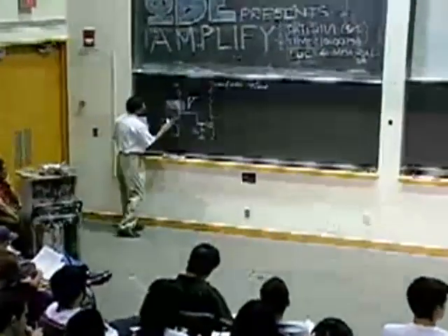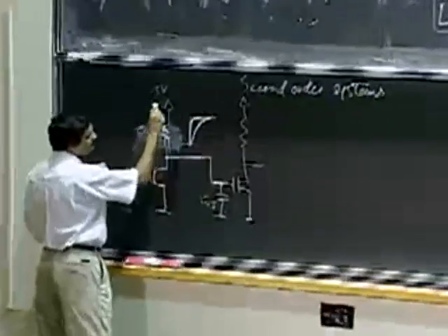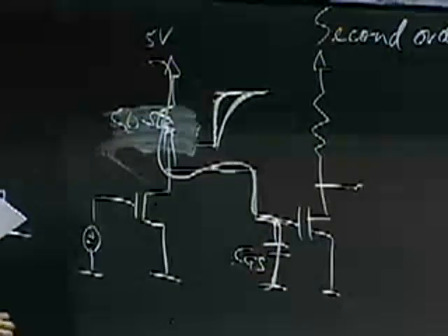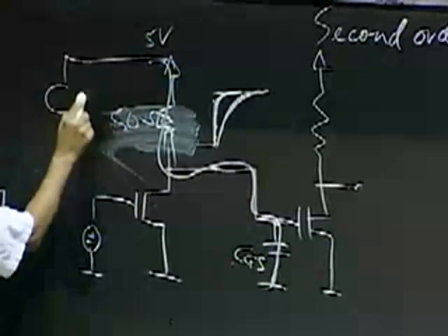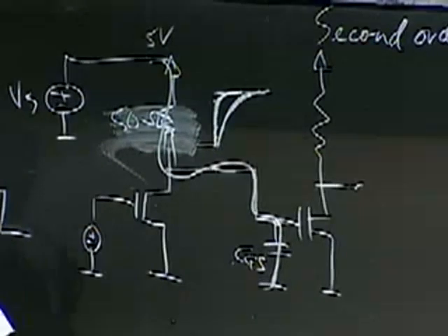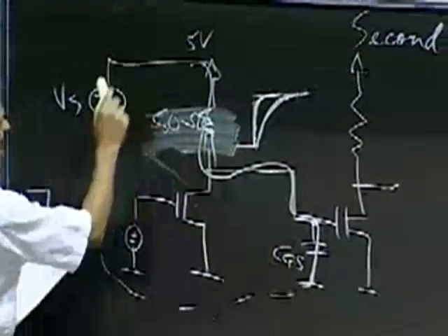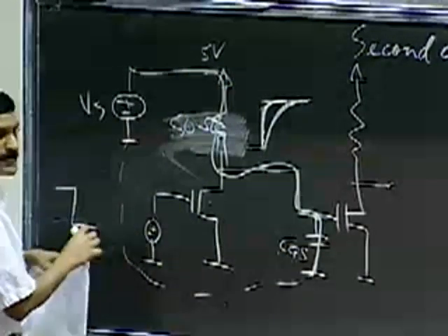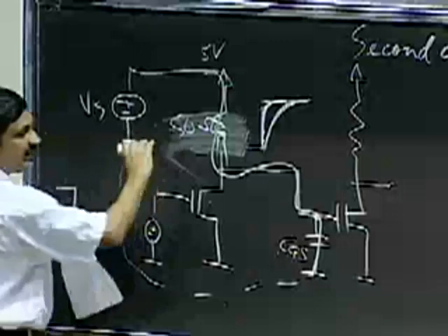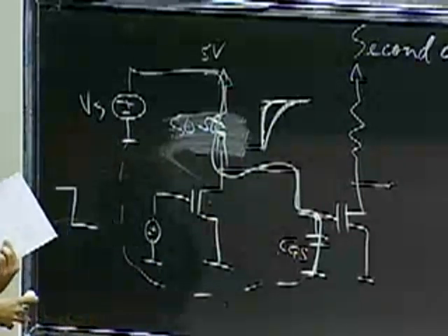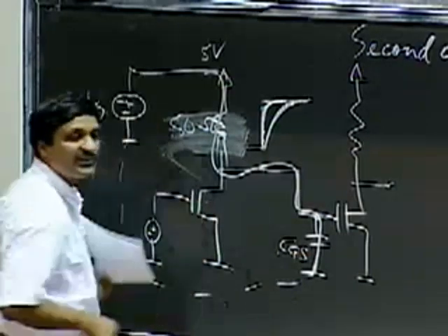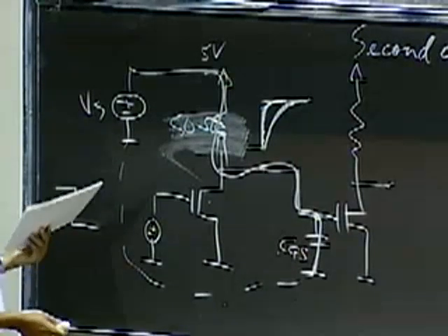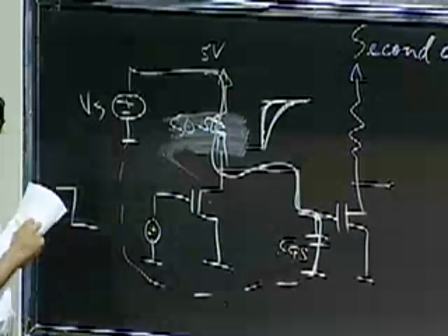What's really going on here is, take a look at this circuit here. But take a look at this path here, okay? And so this is your Vs voltage source. So the path kind of goes like this and around. Okay, turns out that this circuit is a loop here, okay? And when there is current flow, going down to basic physics, you remember that it also encloses some amount of flux, so there's a current flowing in a loop, okay? And because of that, there is an effective inductance here.